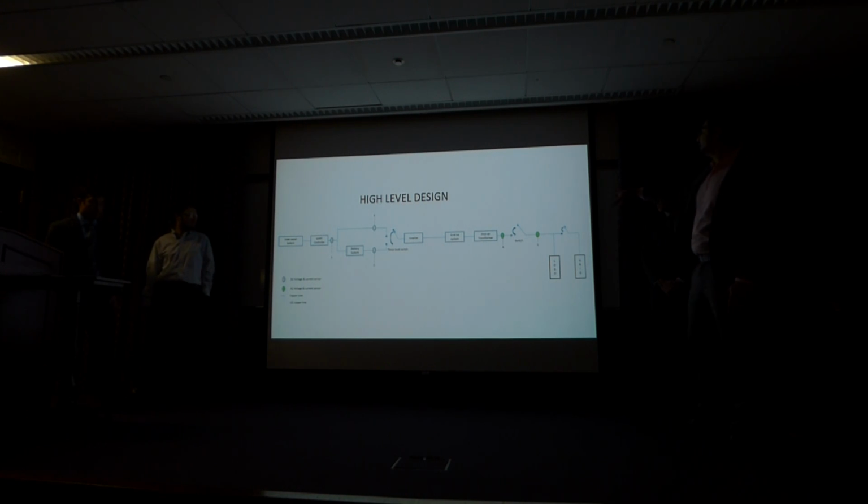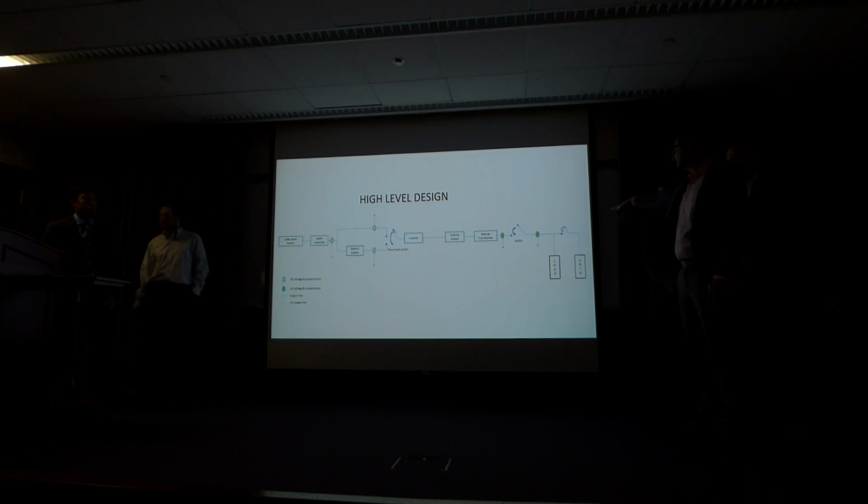So finally, the main controller for our system will operate on these switches. The purpose of that is either we can inject the power directly to the grid, or we can actually bypass the grid, isolate our system from the grid, and just support the load directly. The green ovals that you see in the picture depict our AC current and voltage sensors. And on the other hand, the gray ovals represent our DC current and voltage sensors.